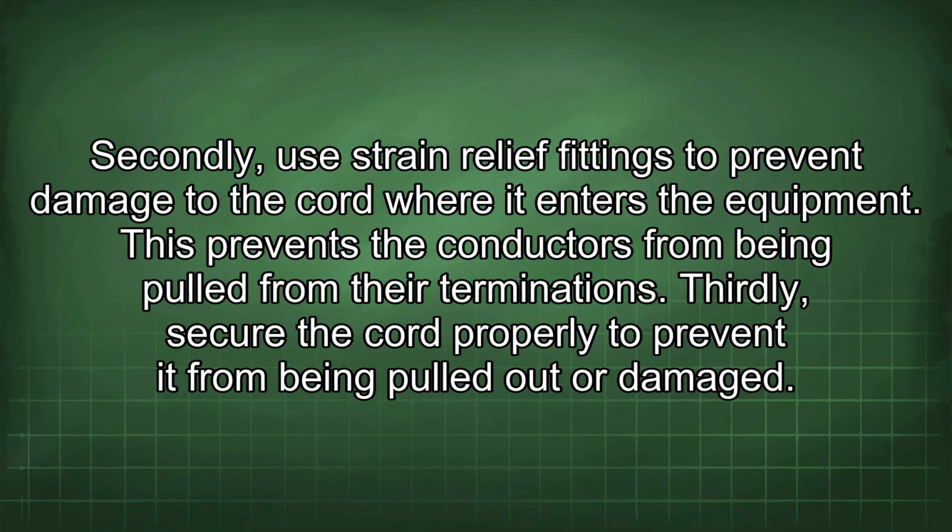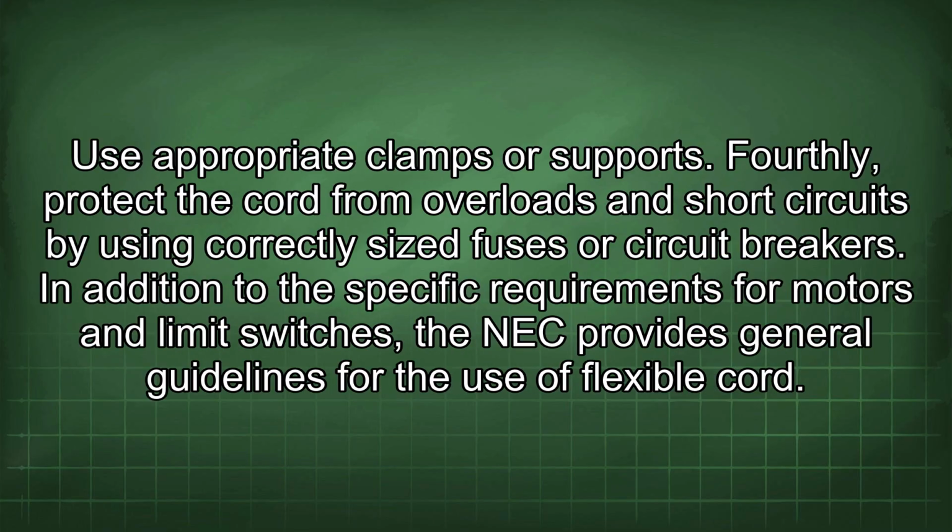Thirdly, secure the cord properly to prevent it from being pulled out or damaged. Use appropriate clamps or supports. Fourthly, protect the cord from overloads and short circuits by using correctly sized fuses or circuit breakers.